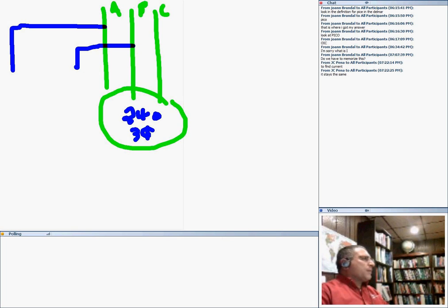And the series circuit becomes very interesting, guys. I have a coil. There's a magnetic starter here that can be driven by a coil. Now, if I lost you, don't worry. There is a coil, and also the overload. Remember, you have to have an overload for the motor. So I have a contact for the load. Also I have the push buttons, start and stop. This is my start. This is my stop.